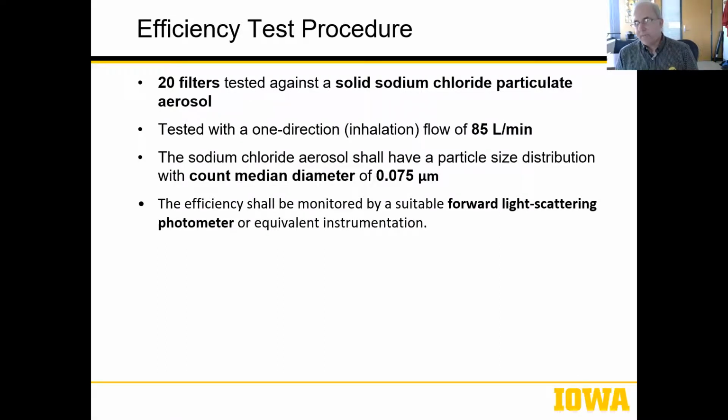They tested at 85 liters per minute. That is your inhalation flow rate when you're out jogging. Let's say it's not super exerted, but it's heavy breathing. So this is kind of a worst case scenario that they developed for industrial situations.